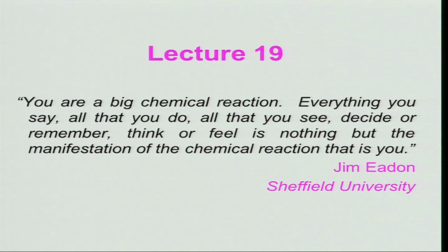I told you nature does a lot of activities through us with the help of chemistry. That is the beauty of this. Let us recall briefly what we had learned in the last lecture. We basically discussed Hess's law, and then we moved to how to find the adiabatic temperature. We found that it is a function of equivalence ratio, inlet temperature, and also pressure.